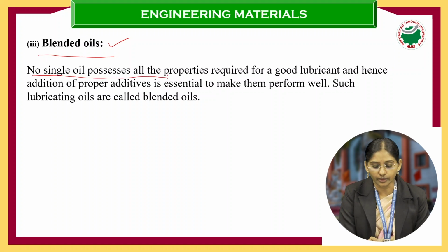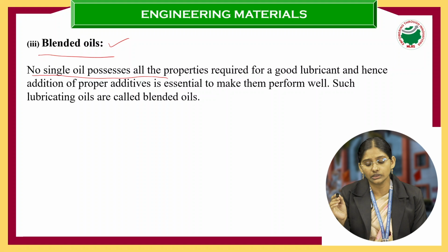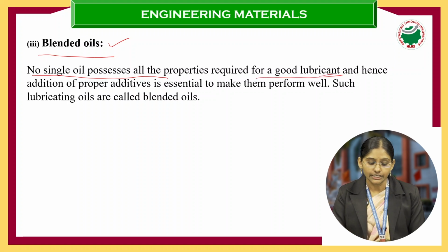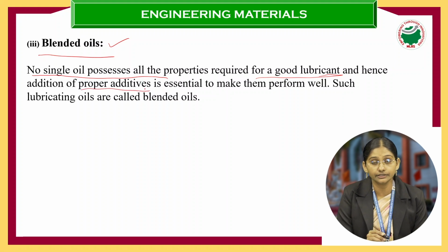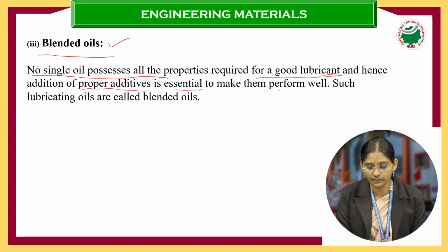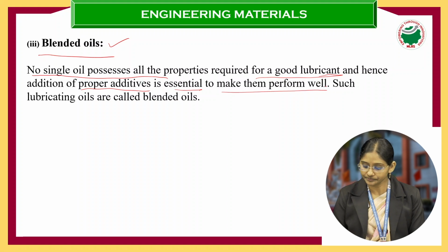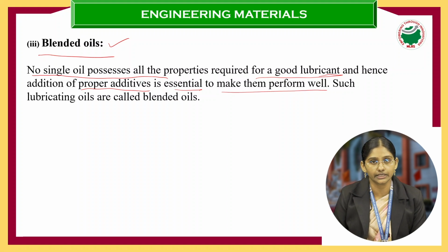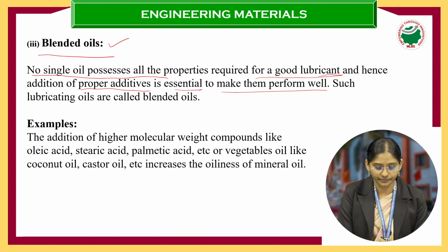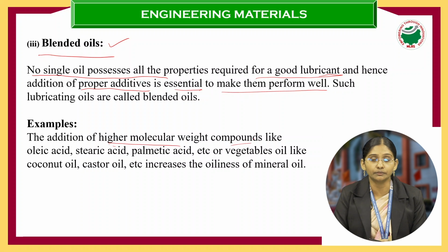No single oil possesses all the required properties of a lubricant. Hence we need to add the proper additives to make them perform well. Such lubricating oils are called blended oils. So what is meant by blended oil? It is the addition of higher molecular weight compounds like fatty acids, such as oleic acid, palmitic acid, and stearic acid, to increase the oiliness of the mineral oil.